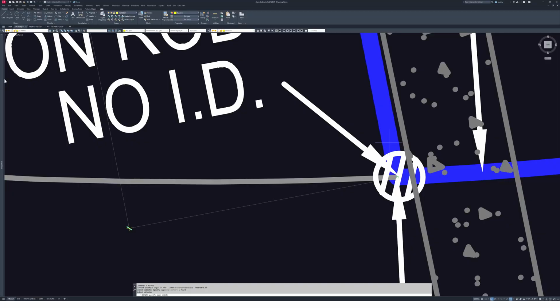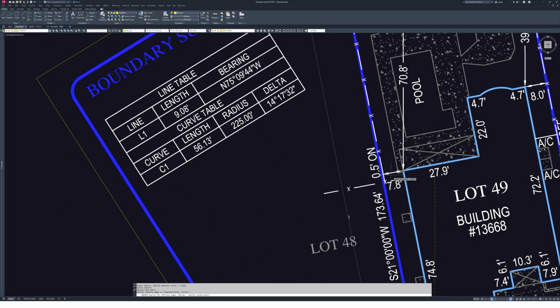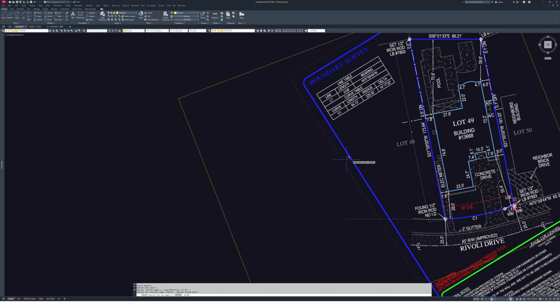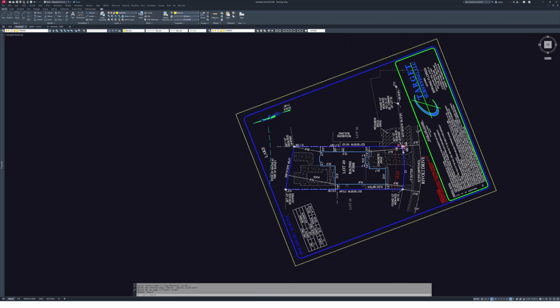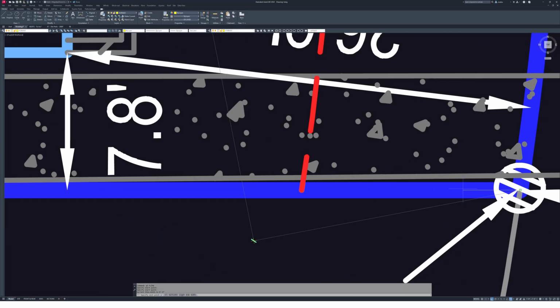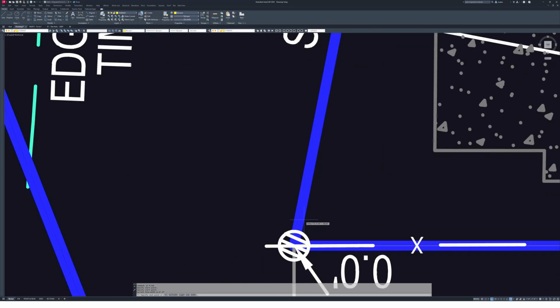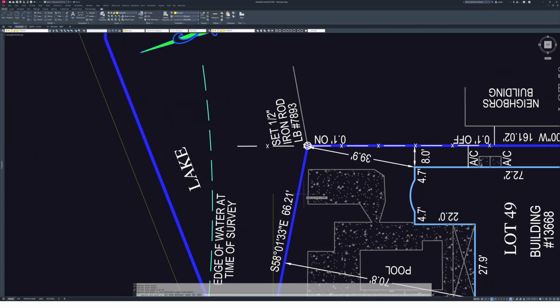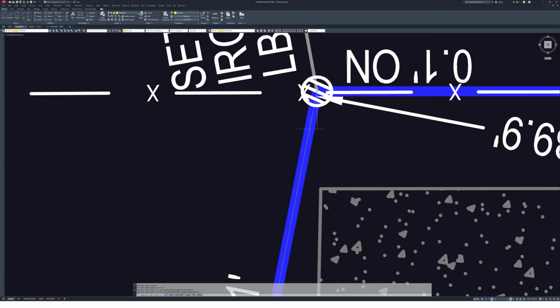So I want to find this base point right here. So rotating, gave it that reference base point, snap to here, and then we'll go flat this way. Now we should be able to go PL for polyline, and I'm going to start right here, and should just be able to trace around this, snapping to these endpoints.